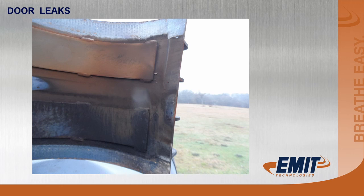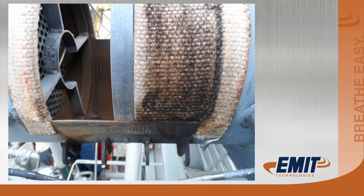Here's a missing gasket is what this one is showing. You can see where the exhaust gases were racing out right here, or on the other hand, they can be drawing air in at the same time. Same with these marks right here. You can see there was no gasket there, and that housing was leaking. This particular unit, they couldn't even get close to meeting emissions.